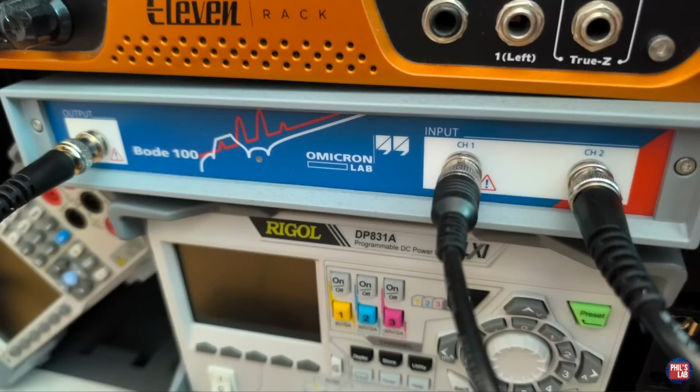For the gain and phase response measurements in the real world, we'll be using a Bode 100 vector network analyzer, but you could of course do this with any spectrum analyzer with a tracking generator, or with an oscilloscope and a function generator. There are many ways of extracting the magnitude and phase response from systems. For this, I'm going to be using the Bode 100 because I can calibrate out the inherent delays caused by the processing platform itself, the analog filters before and after the ADC and DACs, just to make sure we can capture the raw, de-embedded phase and magnitude response of our digital filter, and I'll show you how to do that in just a second.